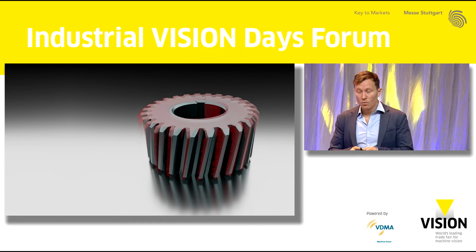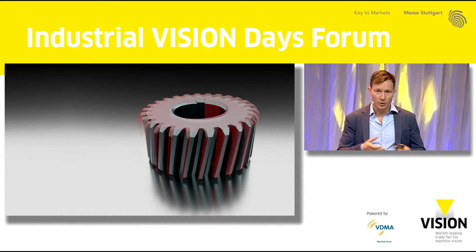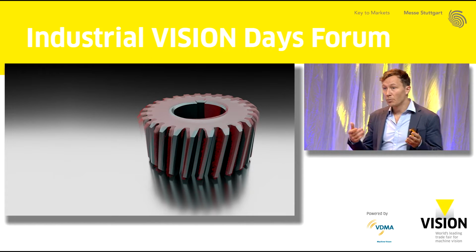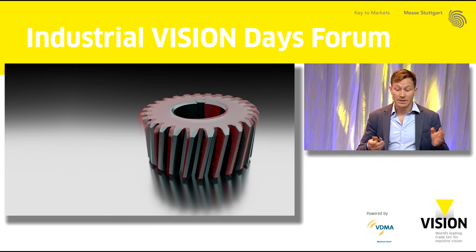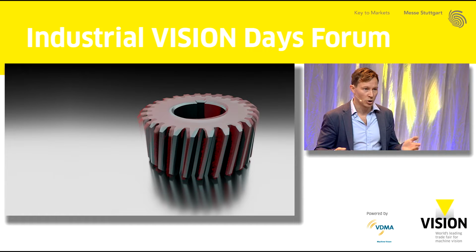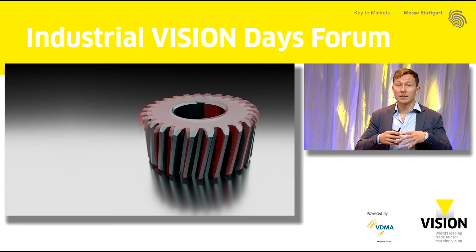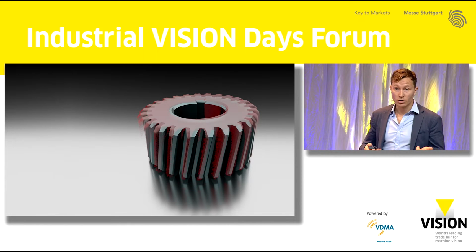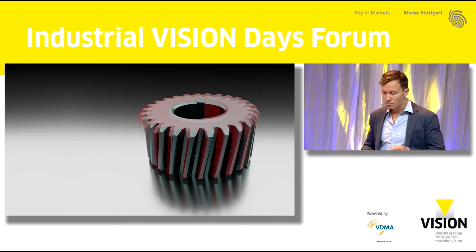When we're interacting with objects in the real world, we really need the coordinate system of the point cloud to match that of the robot and the objects that we wish to manipulate. And this is what trueness is all about. It's about measuring and interacting with objects. So trueness is a term that describes large-scale errors, distortions and deformations. And many of you will recognize them as calibration errors.